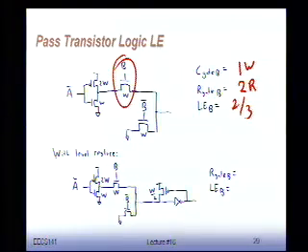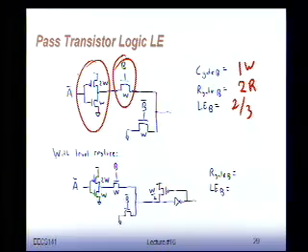Fortunately, if you use this logic family, we're very rarely going to connect through this side here. Definitely in, let's say, FPGAs, all the inputs are always going to be at the gates of the transistors, and those things are going to be fixed values. I'll come back to that next lecture, and show you what you can do with this type of thing to build an FPGA type of device.